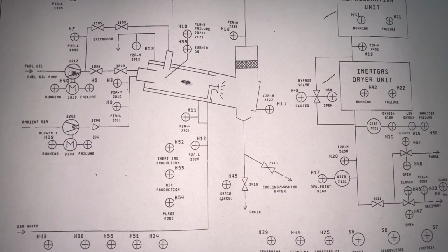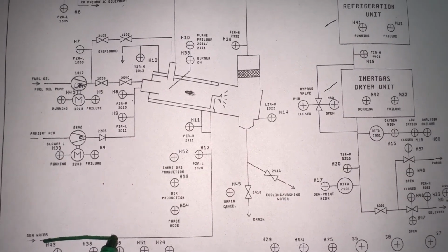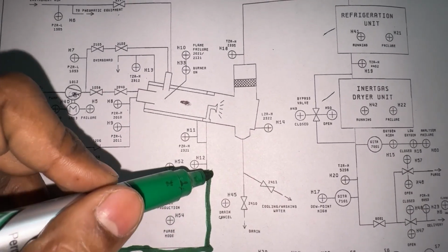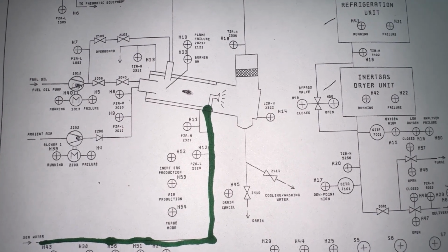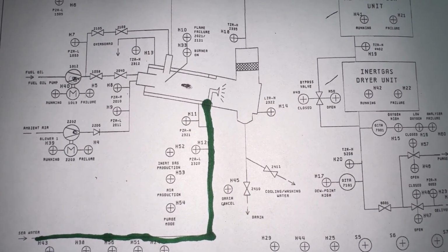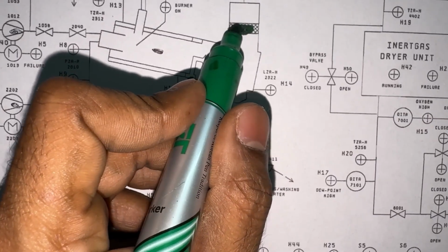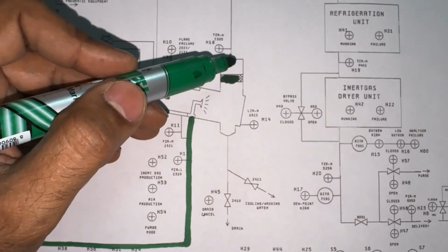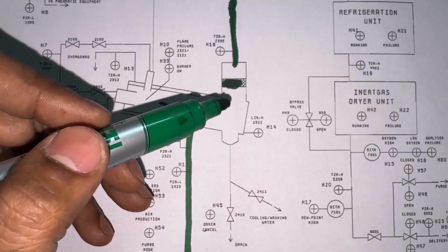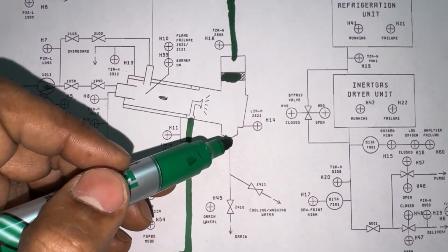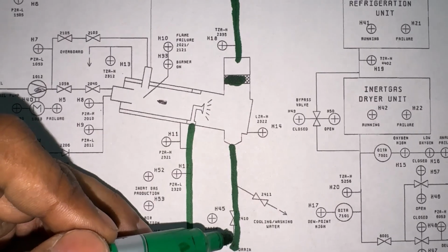So to remove carbon soot from the combustion exhaust, a scrubber is used. This is a scrubber, which has seawater coming in the chamber, and soot is removed from the exhaust and clean IG is generated from the combustion exhaust. Now our IG will pass through the demister. This is the demister. This demister will only let the IG pass, as this IG contains water, so it will not let the water pass and lets only the IG pass, and water from here will go overboard through gravity.